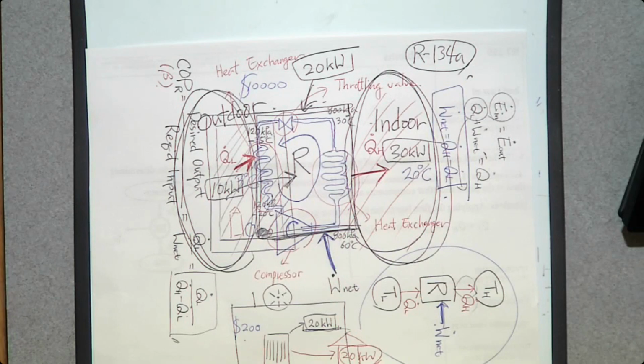The average temperature in a Texas winter could be higher than the average temperature in Michigan. So cooling warm weather is easier than cooling low temperature. So maybe in Texas, you spend 20 kilowatt, absorb 20 kilowatt and dump 20 to 40 kilowatt. But in Michigan, you spend 20 kilowatt, only absorb 5 kilowatt. So the amount of heat dumped here is going to be only 25.